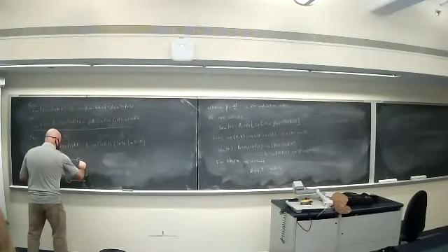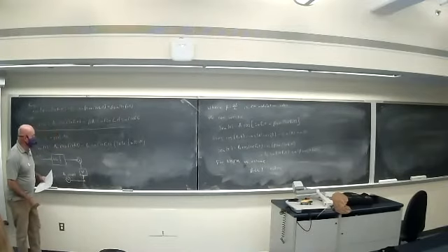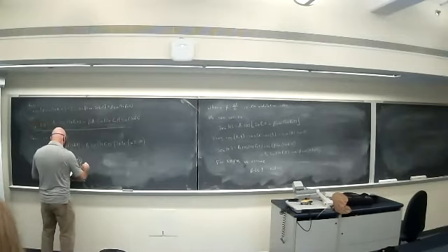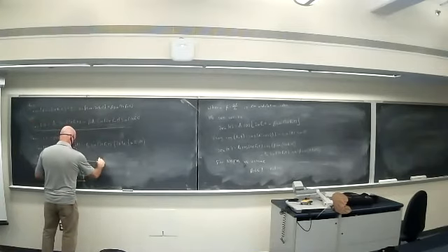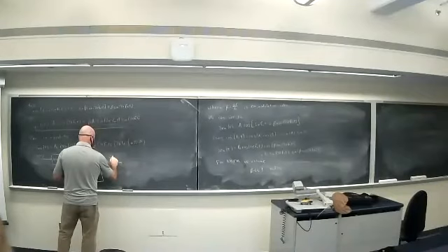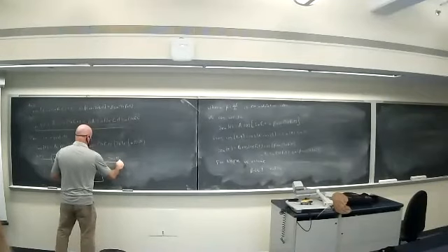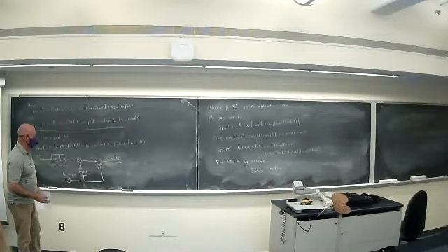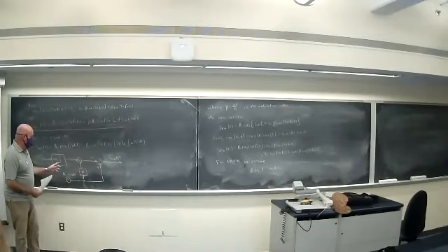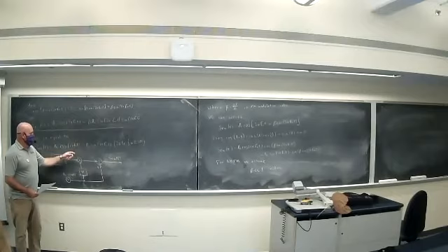A narrowband phase shifter only has to shift at that one frequency to get the sine term. Okay, so I multiply those two together, and then I just add in my cosine. This term is actually subtracted. And it suggests this as a block diagram to create this particular signal.